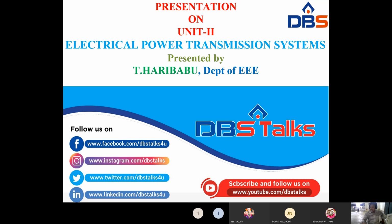So by adding VR, IR R, IR XL, we get the sending end voltage. Vs is equal to VR plus IR R plus j IR XL, right? Like that, knowing the receiving end voltage and current, we have to determine the sending end voltage and sending end current, right?